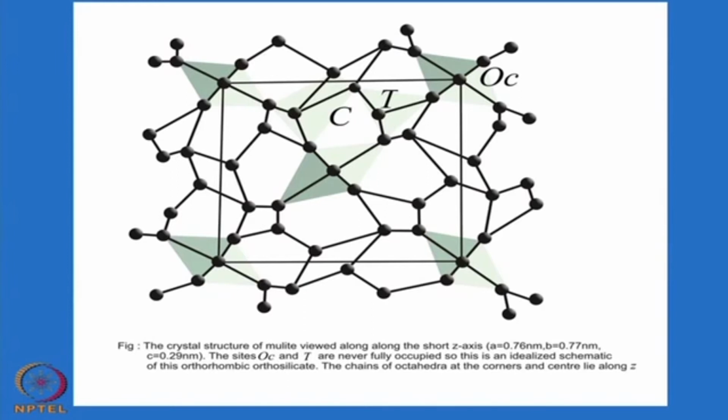aluminosilicate when heated to high temperature, for example, a kaolinite structure. Okay. Kaolinite is a hydrated aluminosilicate. So, at high temperature the hydroxyl goes away, and what remains is alumina and SiO2, and they form compounds, silicates of this nature. So, mullite is one of the very important phases. Whenever any silicate structure is heated to high temperature, mullite is normally formed, okay, and it has a needle-like morphology.